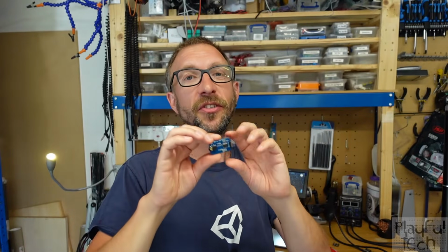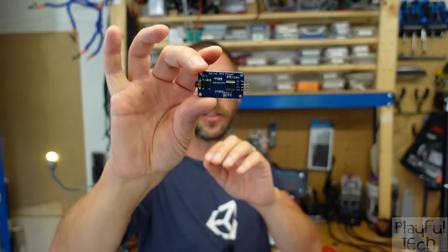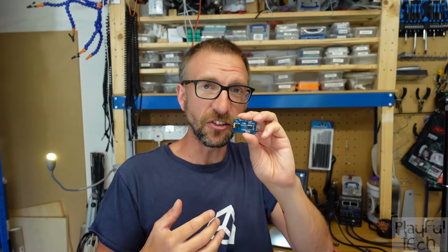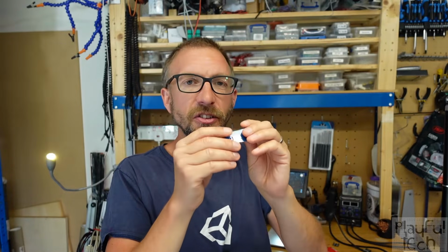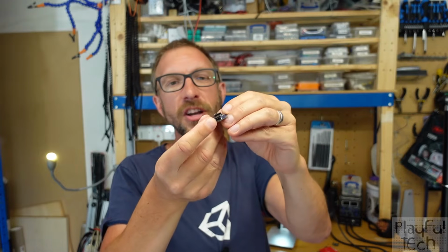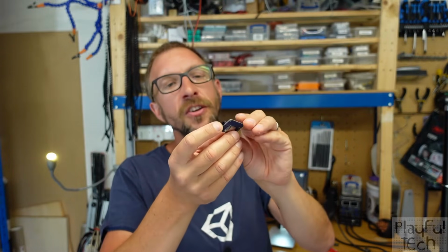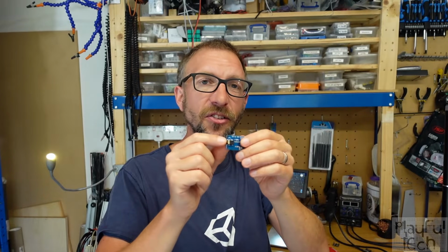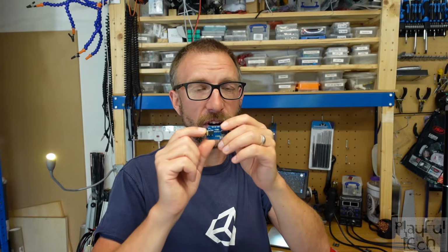Now, as an alternative to the DF Player, there's also boards like this one, which I've also used in projects on this channel. It's often marketed as a Catalex serial MP3 player board, and it's got lots of similarities to the DF Player. The main differences are that it doesn't have an onboard amplifier. Instead, it's got this 3.5mm jack socket, so you can connect headphones or you can use an audio cable to take that signal out to an external amplifier.